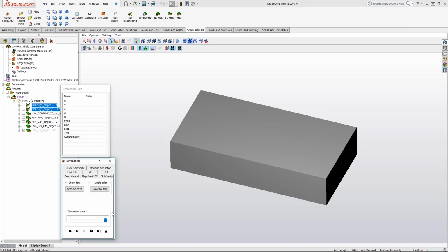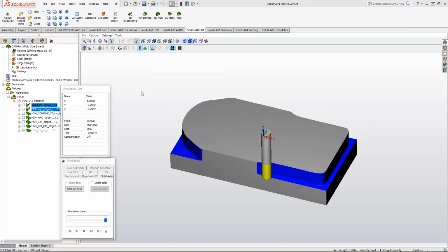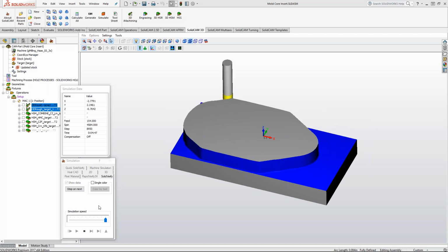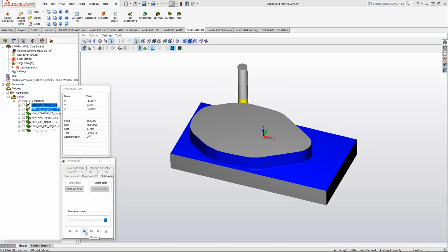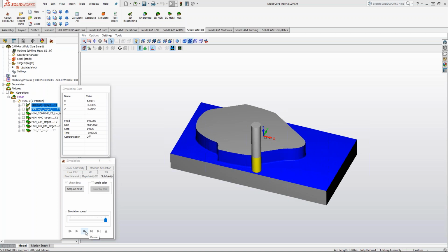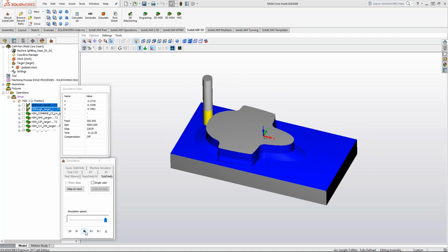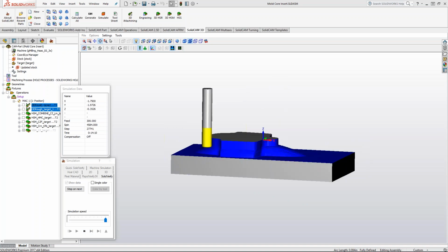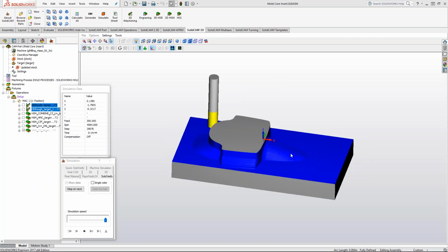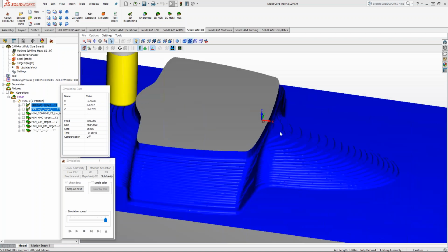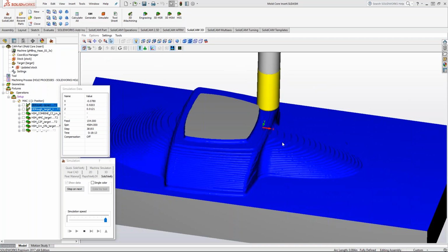And on this one, did you set it as a 30 thou step over, or did you just change that scallop per mold depending on what you're cutting? Well, it depends if I'm going to do a semi-finish pass on it. This one I actually did a semi-finish pass, so I think I did change the scallops to 30 thou, but you can see it's much bigger step overs. So I wanted to smooth it out a little more.